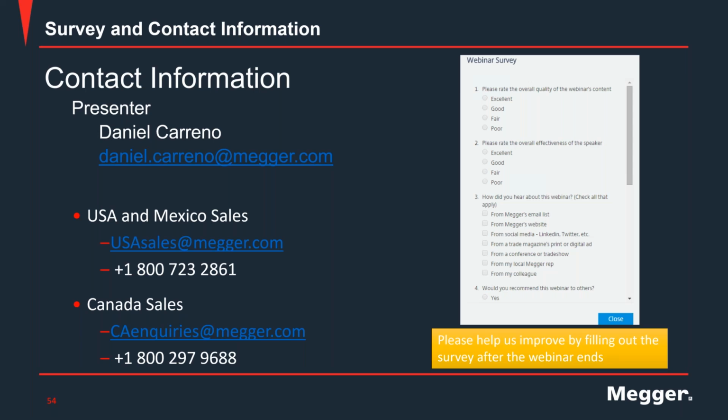So if the results are outside those limits, the first thing you want to make sure is that it's not an operator error. Check your tap voltage. Check your tap position. If you're testing a transformer with a tap changer, make sure you're testing on the right tap position. Because if you're testing on a different tap position, then the nameplate voltage would be different than the measured values that you're getting, and that would result in a higher error.